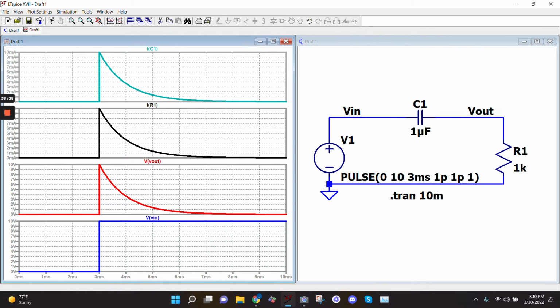He had the next question. What would make a capacitor explode? Okay, there are a couple of different things. Capacitors have what's called a voltage rating. I think I put that on your last homework. That voltage rating multiplied by the capacitance tells you how much charge that capacitor can store. If you exceed that voltage rating, you're putting more charge on it than it can handle, and it'll pop. It's happened, I've seen it in the lab.